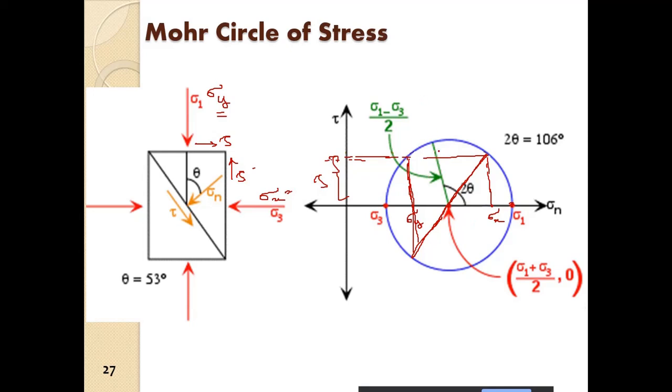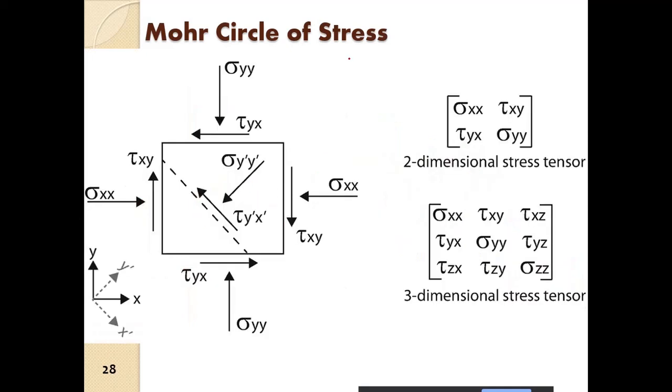All right, so ultimately everything is within this Mohr circle. All states of stress, whether there is shear stress or not: in the principal planes, there are no shear stresses. Whenever there is a slight change in the angle, shear stresses are developed. So as it goes on rotating, we have shear stresses acting on the planes. All right, so that is how you do that.